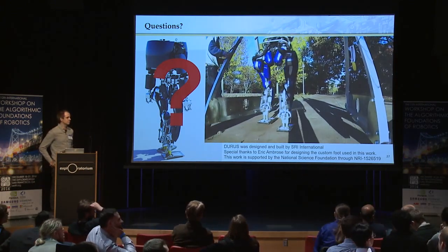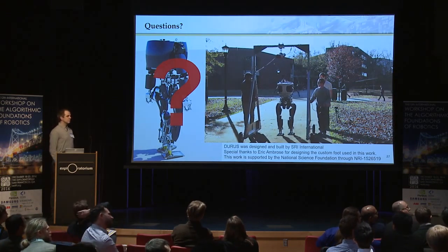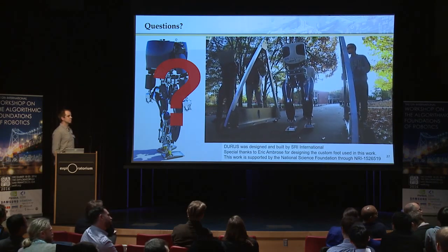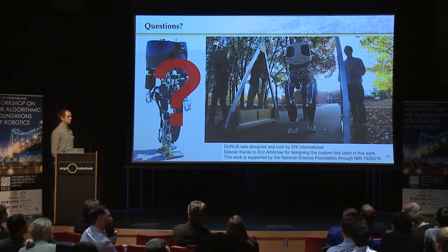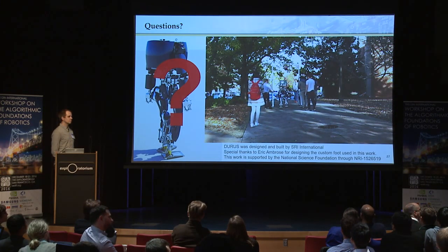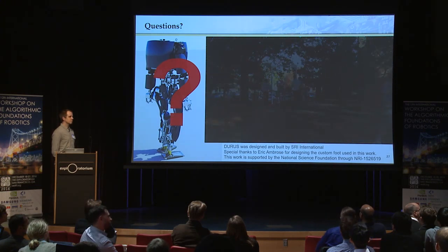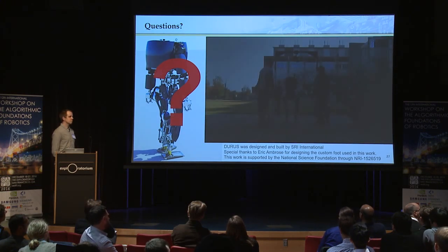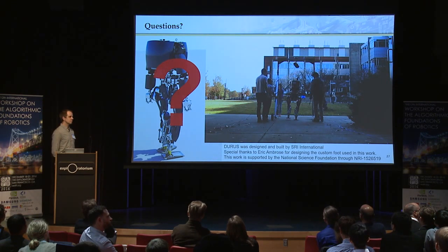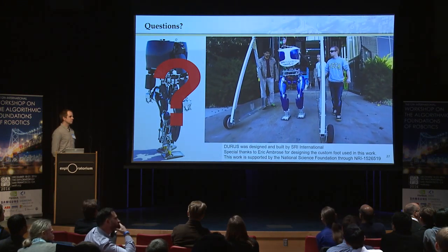Russ Tedrake is our first questioner. Thanks, Joel. So help me understand the energy argument here. You say it's better than flat foot walking, and in the video I can clearly see heel strike, but I don't see toe off, which is what the dynamic walking community would say is the biggest energy economy benefit of heel toe walking: the push off, which would then reduce your future heel strike. I don't see that here. I don't see why the gait itself has changed the energy economy.